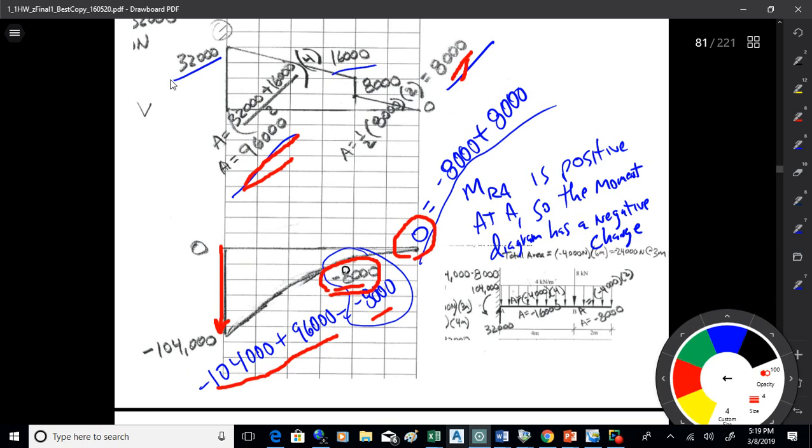All right, I've got a positive slope here and a less positive slope at point B. So that slope becomes less positive, so it's concave down. Similarly, I've got a positive slope at B to the right of B and a slope of 0 at C, I think, at the end of the beam. So that gets me that concave down shape also.